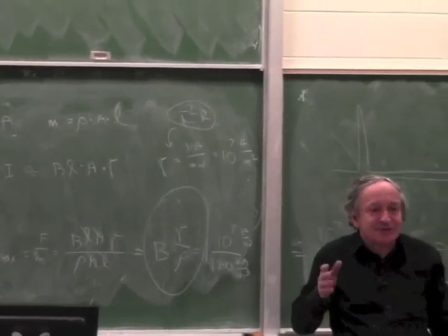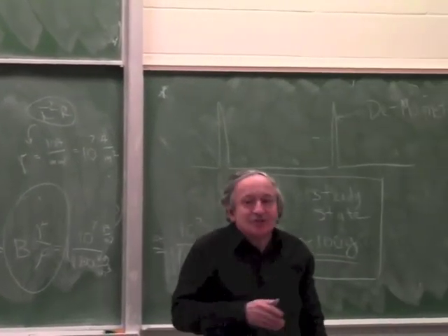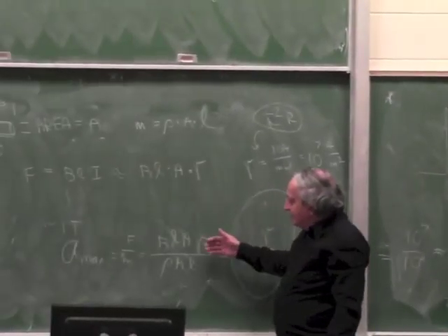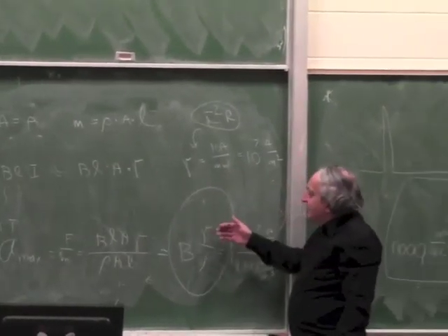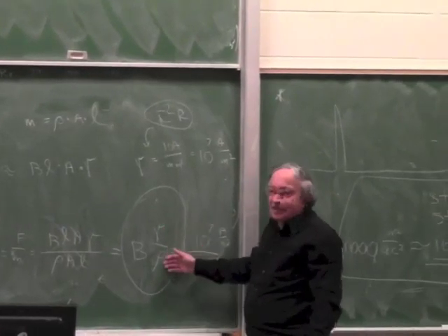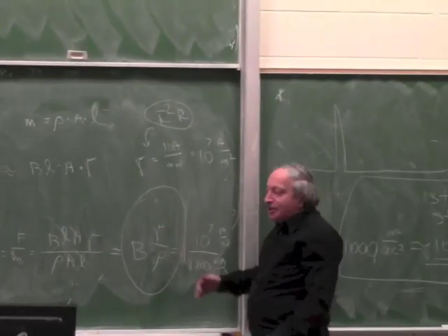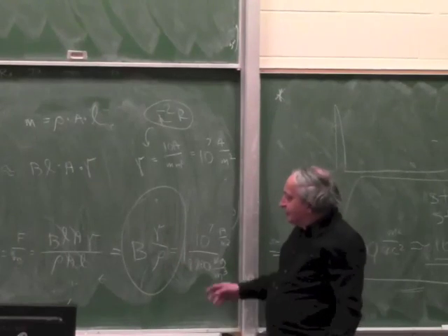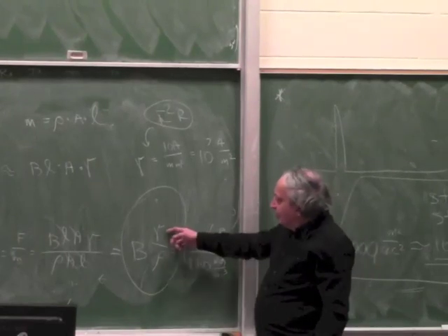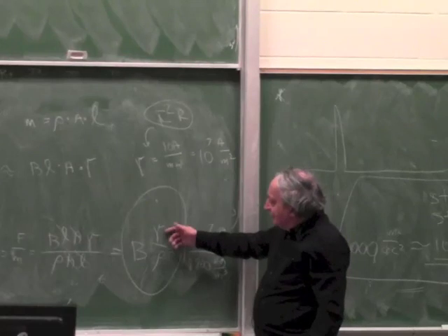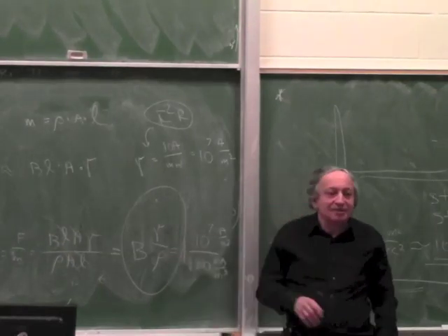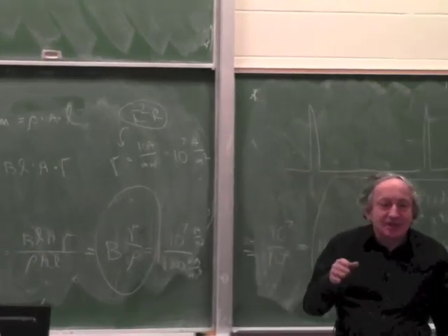of copper. Depends on the alloy, depends on many things. So the ratio of current density to physical density for aluminum is much better than copper. Because this number is 0.6 roughly, and this number is 0.3 or even 0.5 and 0.3. So roughly it's almost double. Again, depending on the alloy and so on.